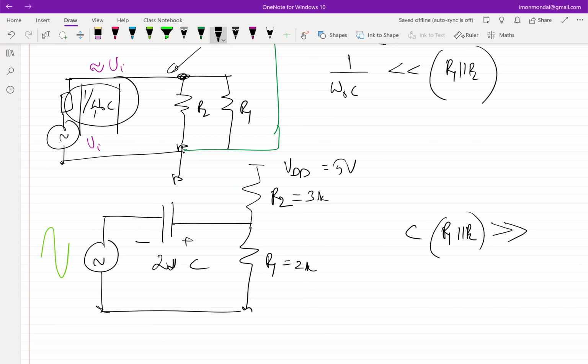Because when we talk about time constants, all the analysis is done for step inputs, right? Where the change happens once and it goes on forever. Typically, that's what time constant means, right? You apply a step and you see how slowly or how quickly it settles to 1 by e of its final value, and so on. That's how time constant came, isn't it? So whenever we are talking about time constant, at the back of your mind you are essentially saying the kind of input we are dealing with is a step input. Correct? But here we don't have a step input.